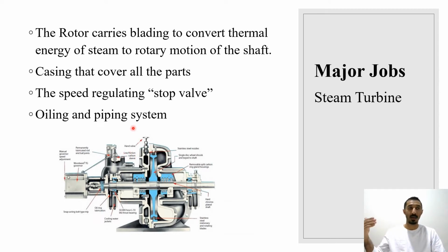So basically a 625 psi steam line comes inside the turbine, rotates the blades of the turbine, and moves the rotor, which drives a motor or a pump, and the steam comes out from the other side at 60 psi.